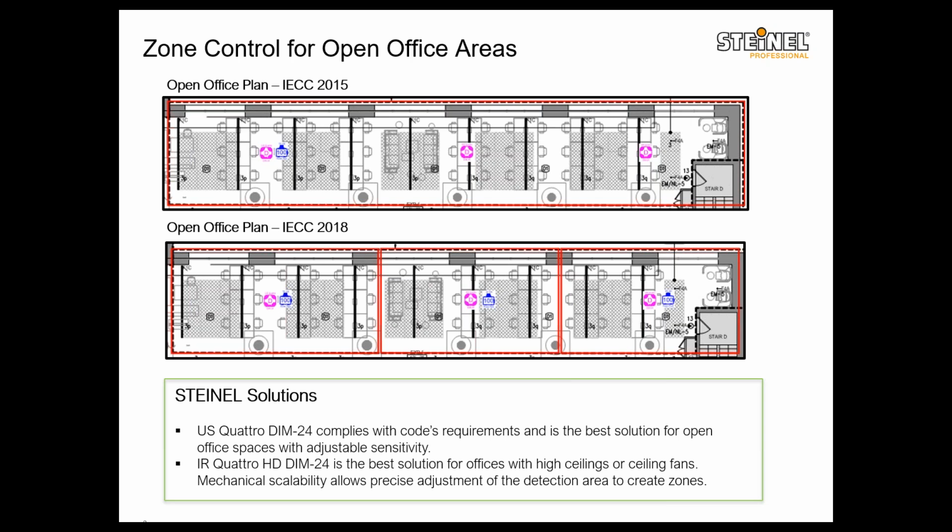And if we assume that, like previously, you had one daylighting zone with daylight responsive control all the way across the top for the whole area, now that also needs to be split into 3, which means each of those zones will have 2 sensors, 2 power packs, and override switches to meet the new code requirements.